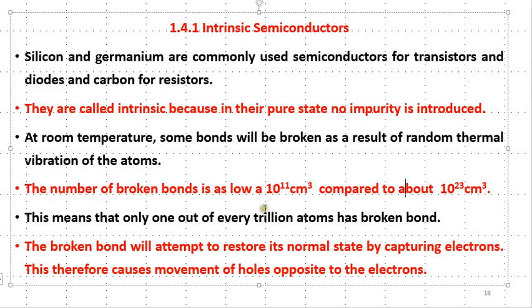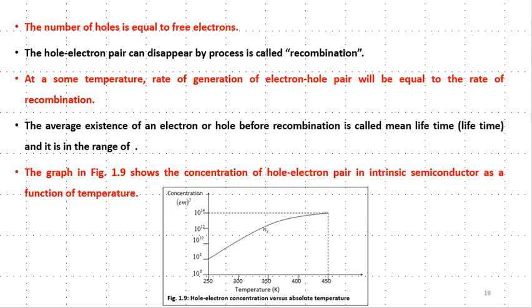So what we are saying here, the pure semiconductors which are intrinsic, have a very low amount of conductivity, because on average only one bond out of 1 trillion is broken as the temperature rises. So this conductivity is not sufficient. And if we want to look at it in a clearer picture, look at this diagram giving us the number of bonds broken with respect to the rise in temperature.